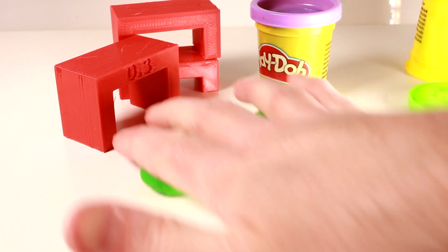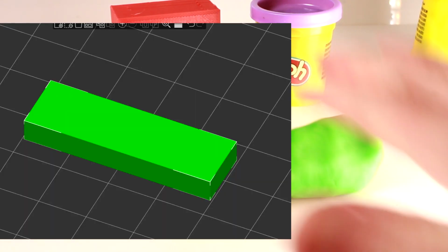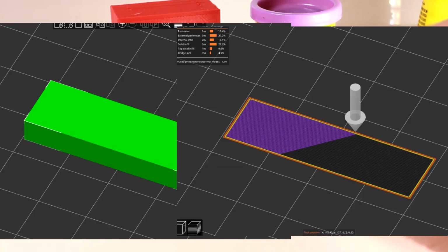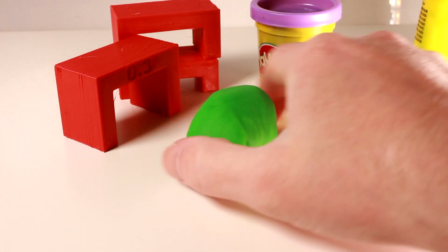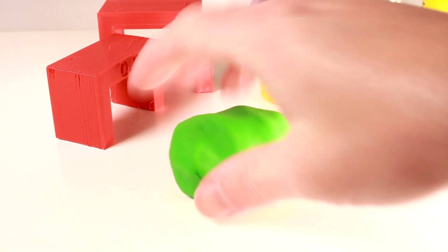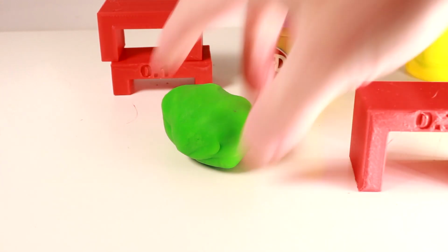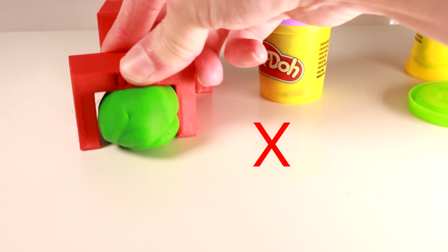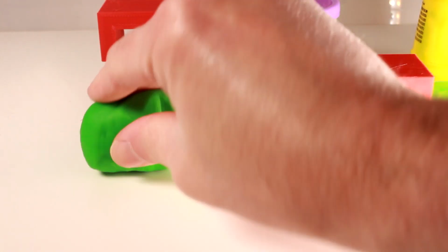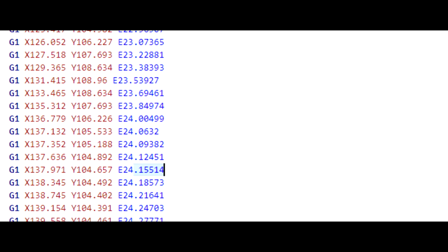The fundamental aim of a slicer is to convert a solid object into horizontal slices, each made up of individual lines of extruded filament. Obviously. But the balance between the parameters you supply and the amount of filament supplied to the nozzle in those G-code commands is a calculation that the slicer does, and the slicer cannot afford to get that wrong. At all. The slicer must know exactly how much filament to extrude for each G1 G-code command. If you look at the G-code, it can seem like the numbers are a bit random, but of course it's not. It's really hard to understate how important this particular calculation is.